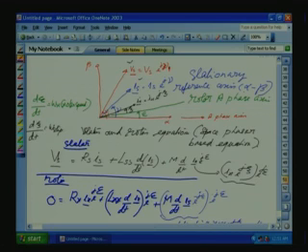Now, for the voltage term, this current originally defined with respect to the rotor axis, we have to bring to the stator axis. That is why the angle is increased now. Rotation is in this direction. So now the new angle is theta plus epsilon. Theta is already inside this IR underscore. So this is the current. Now, once the rotor current is defined with respect to the stator axis, the voltage term is equal to M into d by dt of this one.